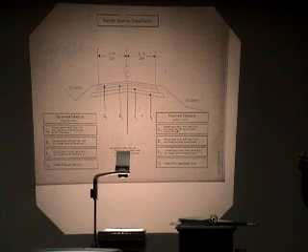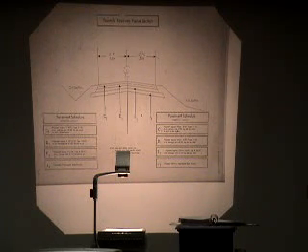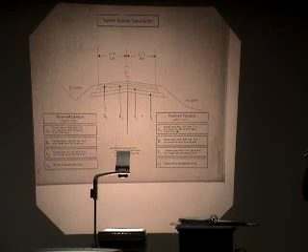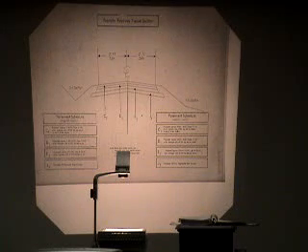Could run into problems on the job site. It's primarily because different mixes are composed of aggregates from different quarries which have different specific gravities, and that causes the unit weight to vary slightly from mix to mix. And so 168 pounds may not always be exactly 1.5 inches because of those differences. And that's why it says an approximate rate and an average thickness.